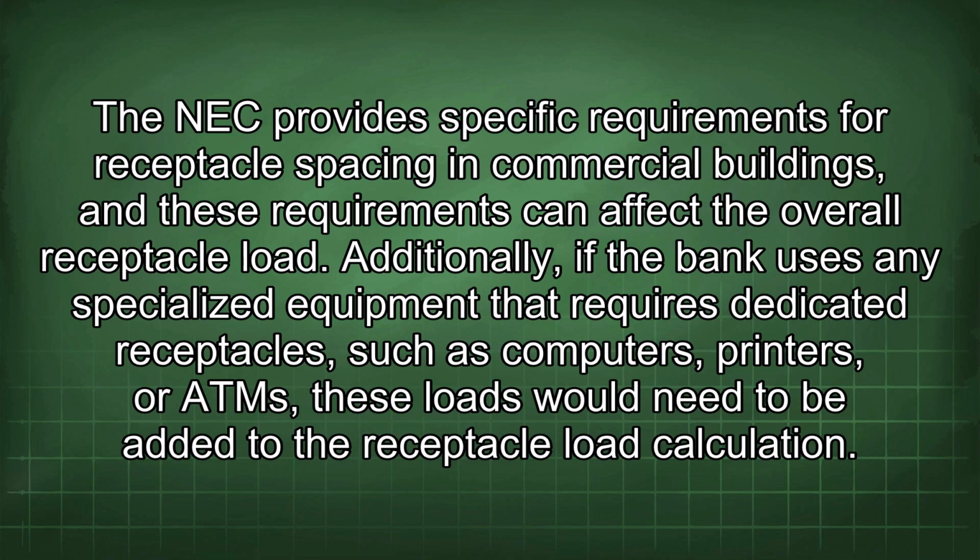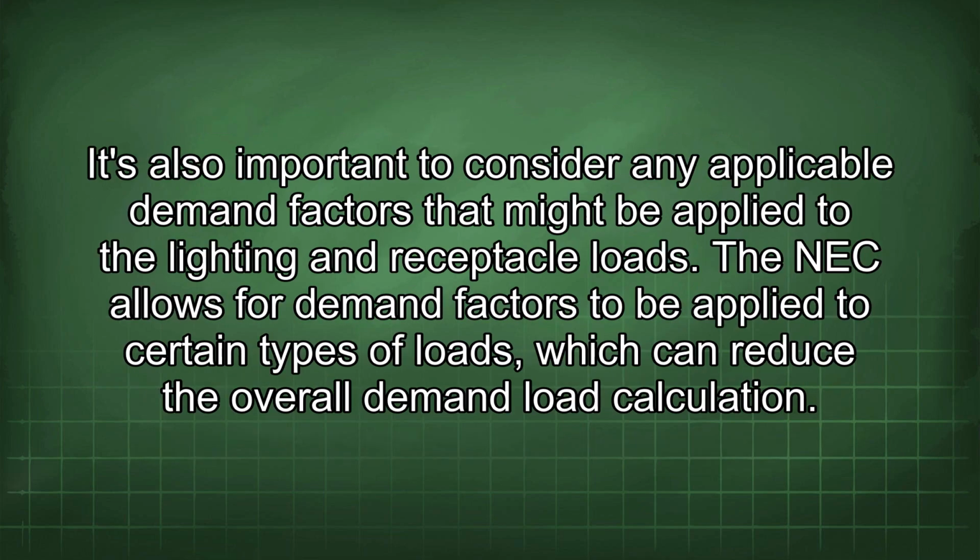Additionally, if the bank uses any specialized equipment that requires dedicated receptacles, such as computers, printers, or ATMs, these loads would need to be added to the receptacle load calculation. It's also important to consider any applicable demand factors that might be applied to the lighting and receptacle loads. The NEC allows for demand factors to be applied to certain types of loads, which can reduce the overall demand load calculation.